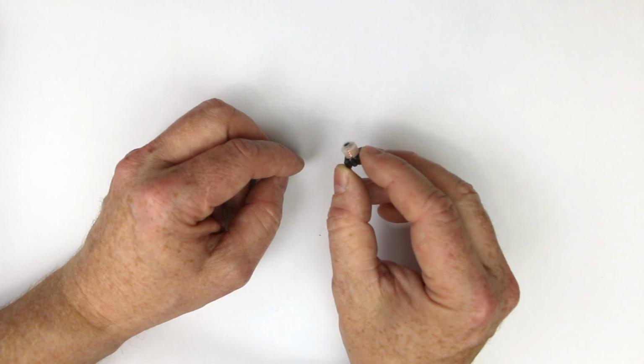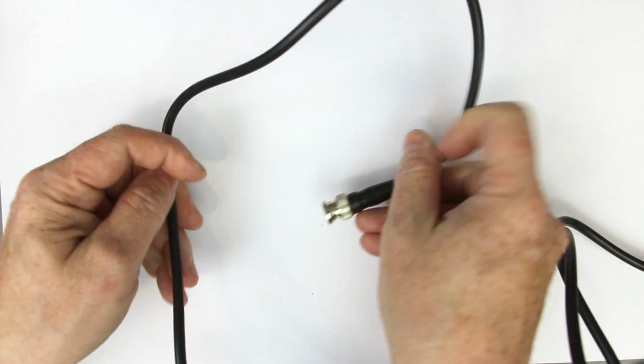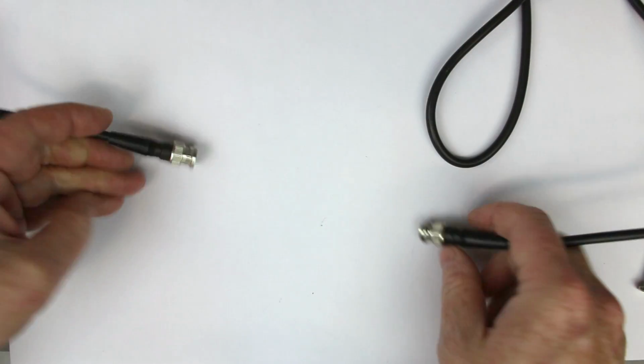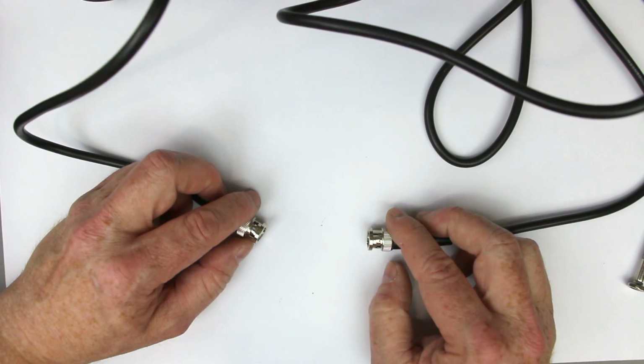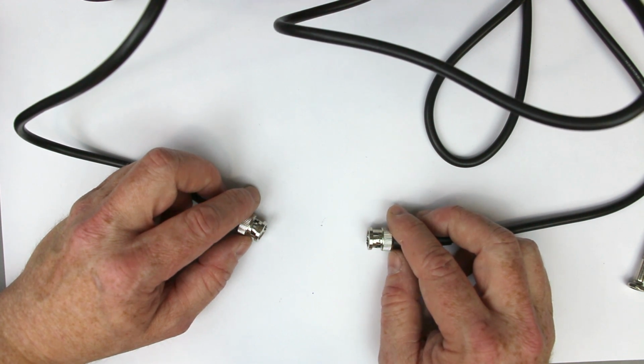So magnetic antennas, as we call them, may take several looks and shapes, and you won't believe it, but even forming a loop out of a piece of coax cable works. I can't show you the full extent because the field of the camera is too small, but imagine I would form a big loop of one winding with a piece of coax cable. Even this is a magnetic antenna, and not the worst one.